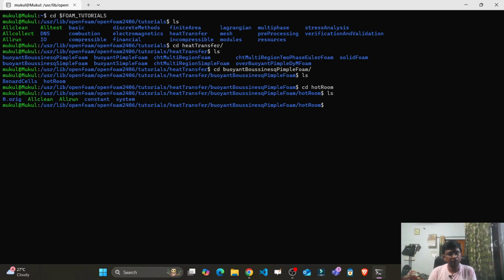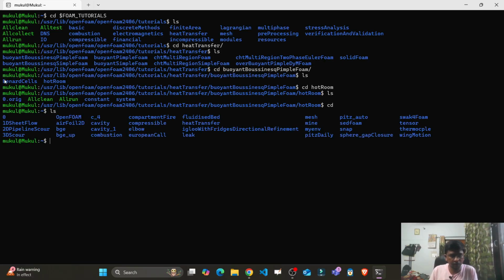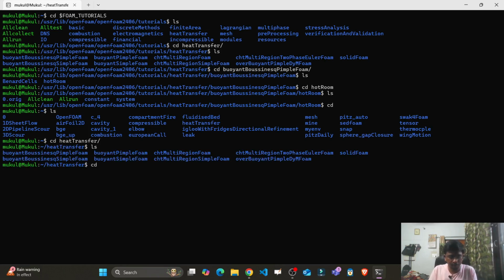All right, so as in the Benard cell tutorial, if you have not watched, please go and watch it. There I have told you all that I've already copied the whole heat transfer tutorial to my home directory. So I'll be going to my home directory and simulating there this hot room tutorial. So let's go back, press cd, press ls. Okay, so you can see that the heat transfer tutorial directory is there. So I have to go there, go to buoyant Boussinesq pimpleFoam, and there you can find hotRoom.